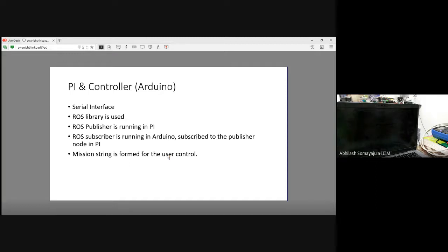Okay. So what you publish from the Pi to the Arduino should be the RPM of the prime mover, which is the BLDC motor, and the angle at which you want to hold the rudder. Commanded rudder angle, commanded RPM. Those are better to have at hand rather than the speed, because once you talk about speed, you are kind of throwing a whole lot of the physics of the hydrodynamics out of the window. And you are saying that I'm open loop calculating it. It may not be valid for different situations.